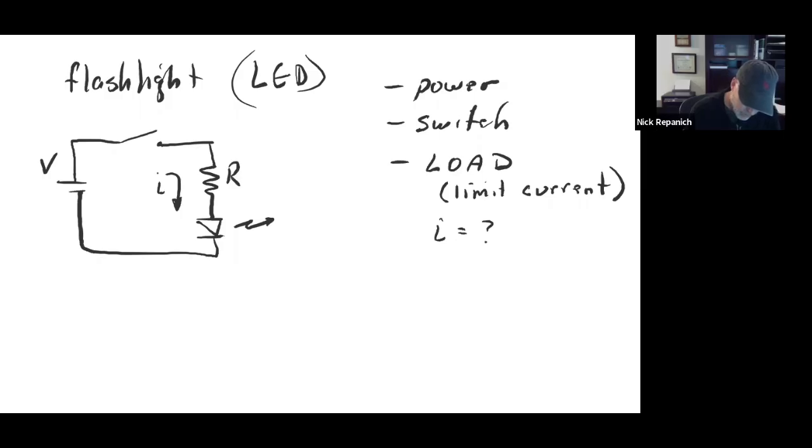And in fact, then you can calculate I, which is super easy, V over R. If you decide to count the voltage drop across the diode, that's fine. You don't have to. If you wanted to be truly accurate, you would. But remember, we're not doing much that's super accurate. We're trying to pick the size of the wire, and we're trying to make sure it doesn't burn up the transistor.